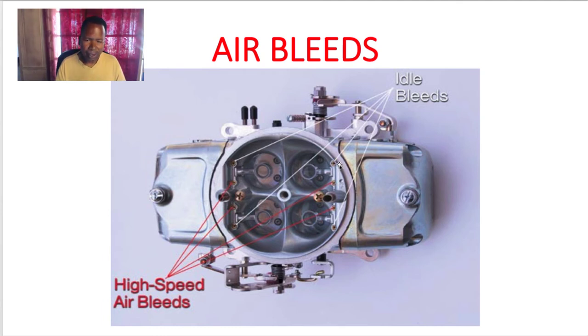Here's the air bleeds. Now the air bleeds have to be cleared. If they're not clear, you get siphoning effect, you get dripping carburetor, and the air fuel mixture obviously ain't gonna mix properly. I hope I'm pronouncing that word right, emulsifying, something like that. But anyway, when you clean out the carburetor or servicing the carburetor, these air bleeds have to